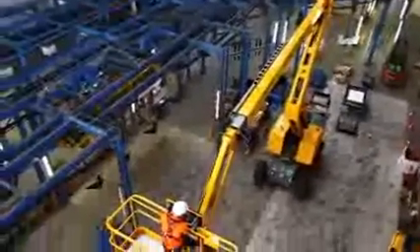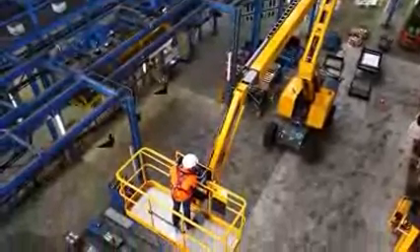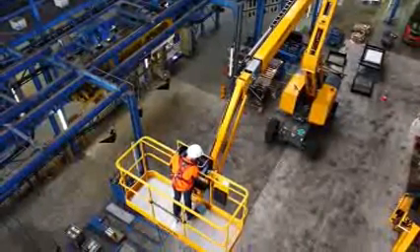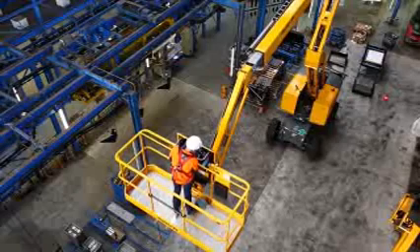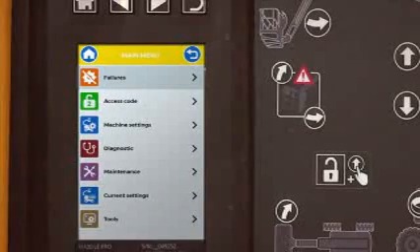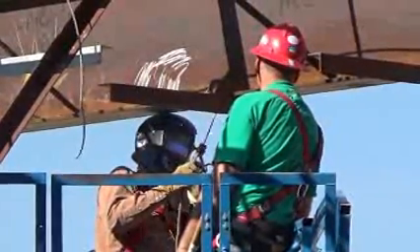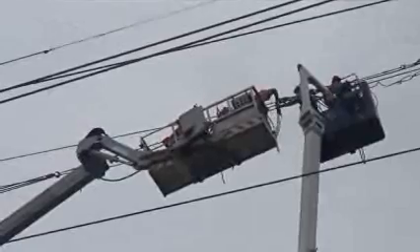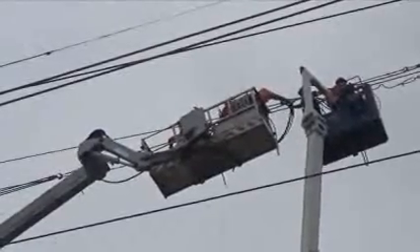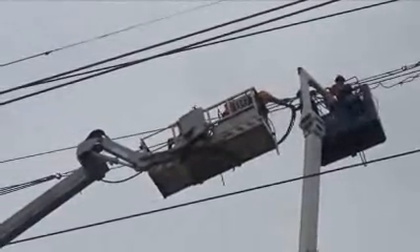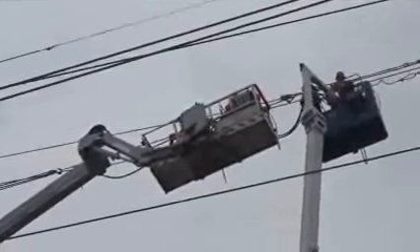Some of the rules include: platform occupants must always maintain firm footing on the MEWP flooring. Immediately stopping operations if any problem or malfunction occurs during operations or the operator becomes aware of a hazardous location or atmosphere. Avoiding entanglement of the MEWP or adjacent structures with rope, electrical cables, and hoses.